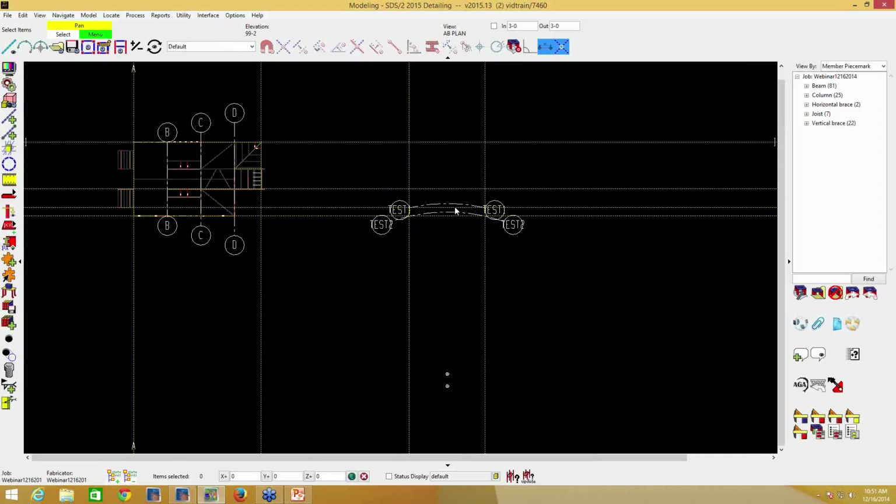With these curved and circular grid lines, you will have a center here for your arc. If I come up here and change my selection filter to grid line and highlight over this, you can see that it's got a center there for the curved grids. If I need to add in a construction line, I can use construction line and then exact point, and it will pick my grid center here of my arcs.